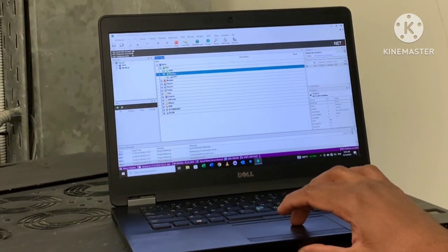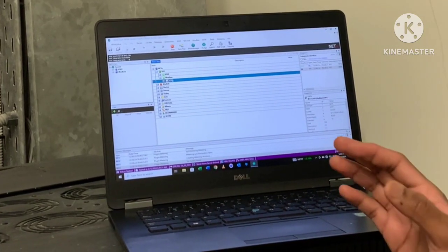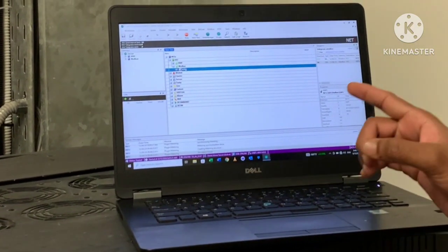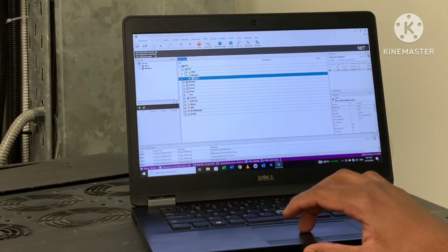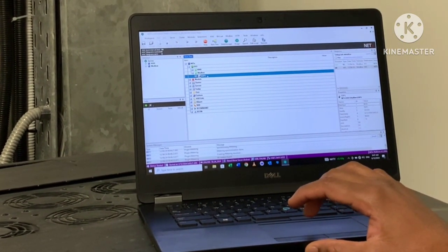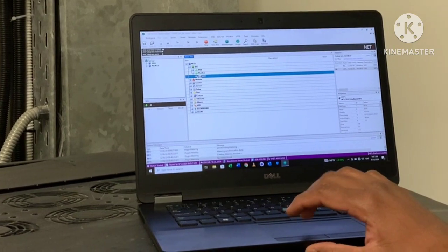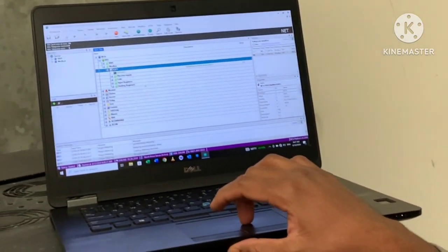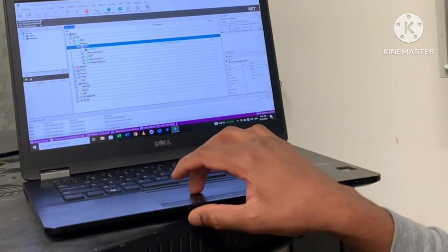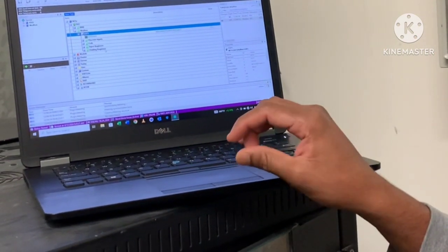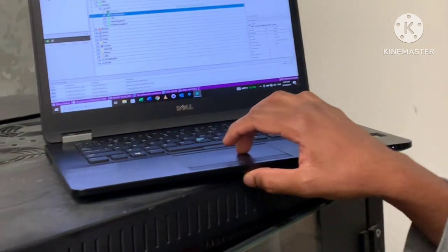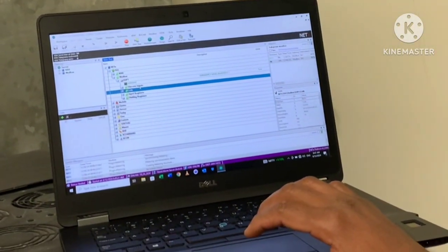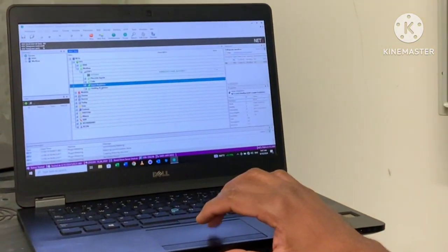So in this case, we will move to the Modbus branch. As you can see over here, it's showing the EDP1. So once I am integrating the Modbus device, I write the name I want. So at that time, we wrote the name as EDP1 because the panel name is EDP1. Once you click on EDP1, it will show you some branches. Okay, each branch is for each type of register. Okay, these two are for the discrete inputs and coils, which are for the digital values, and the rest of the tools are for analog value.